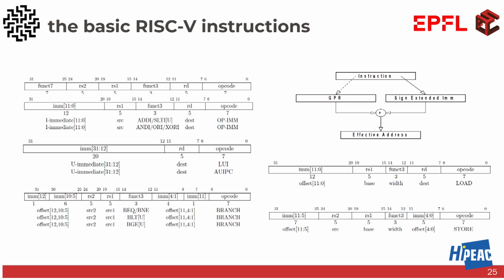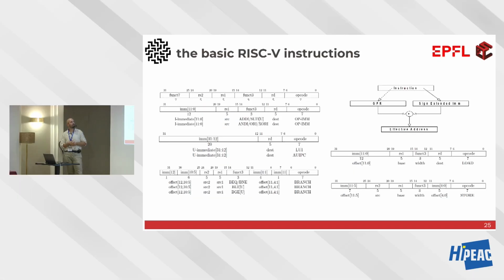Yeah, but what I didn't say, and it's important to say, is that it's a RISC architecture, right? So you cannot have instructions referring to memory. Those are CISC architectures. You need to have operands in registers, so you need to communicate with the memory in an explicit way. This is done with load and store, yes, because RISC-V is a RISC architecture.